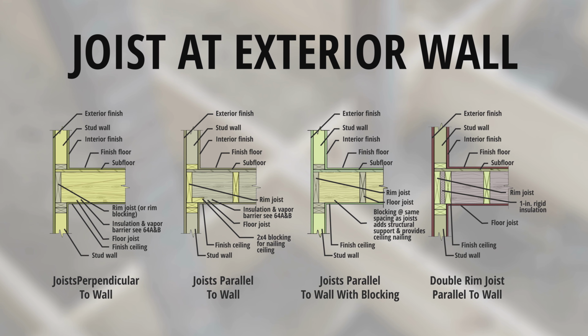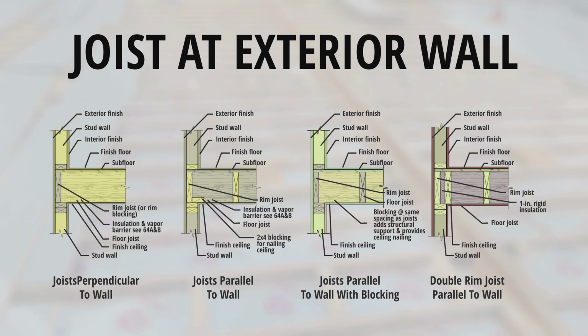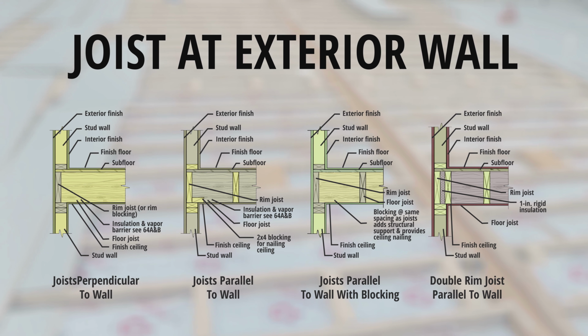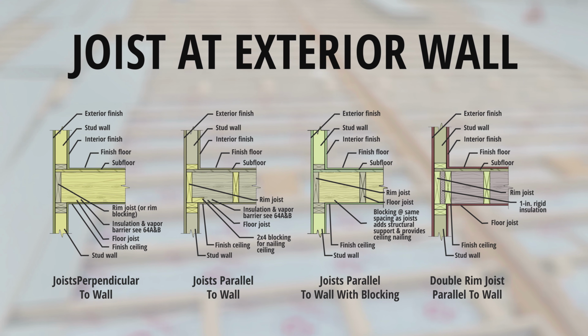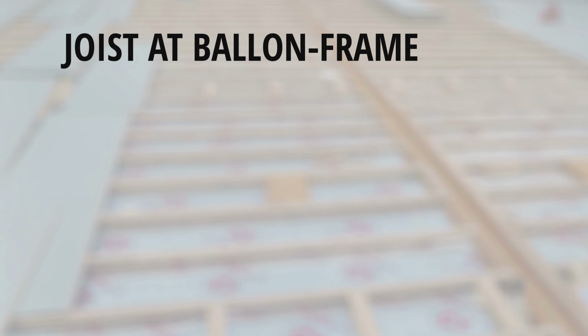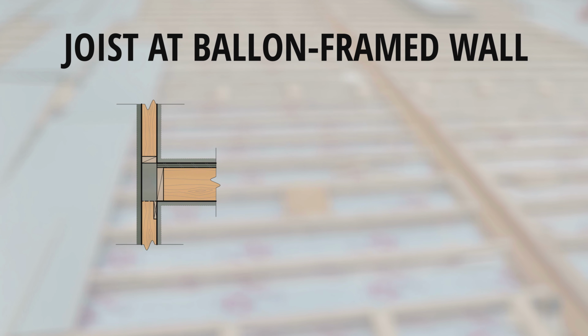D: Double rim joist parallel to wall. Exterior finish, stud wall, interior finish, finished floor, subfloor, rim joist, 1 inch rigid insulation, floor joist, finished ceiling, stud wall. Joist at balloon framed wall. Let's take a look at these 2 illustrations.